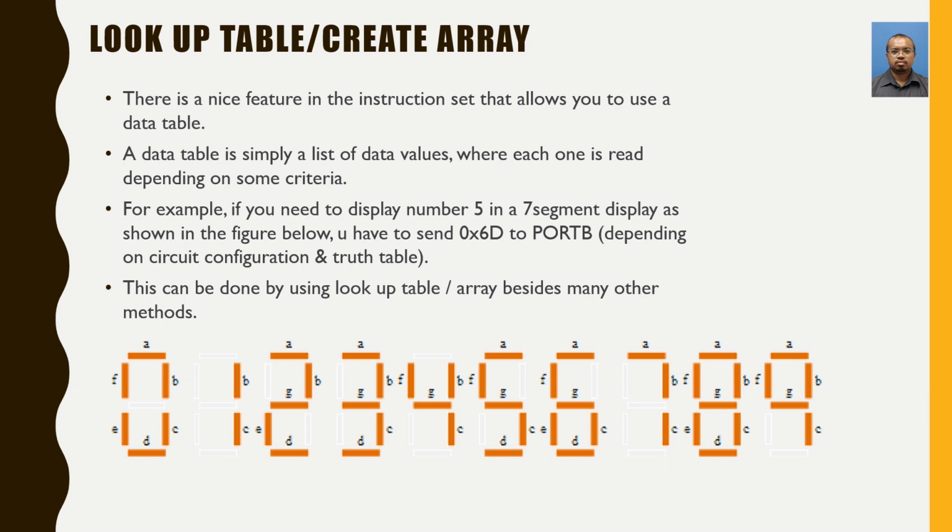Right, lookup table or create array. There is a nice feature in the instruction set that allows you to use a data table. A data table is basically a list of data values where each data is read depending on some criteria. For example, if you need to display number 5 in a 7-segment display, as you can see down here,